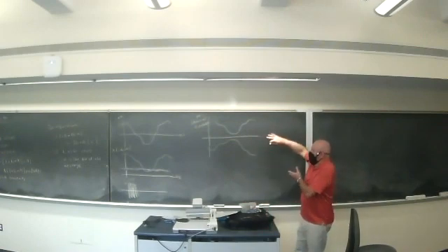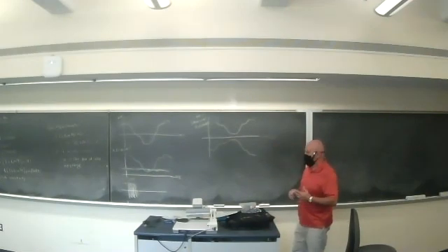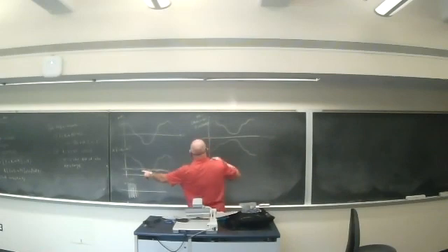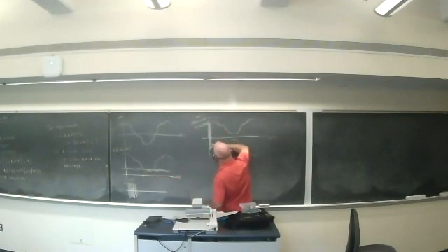Now, this is actually called the envelope of the signal. What the product would really look like is this multiplied by plus 1, and then minus 1, and then plus 1, and then minus 1, right? The actual waveform is going to follow the cosine. When the cosine is 0, this is 0.